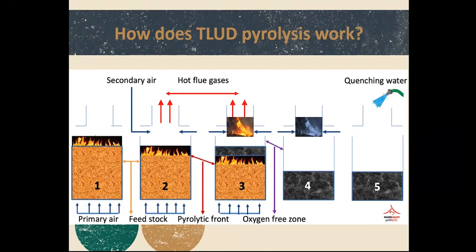So when we're done with that, we'll quench it with water, and we'll stop the process, and we will prevent the remaining material in the barrel from turning to ash. We don't want it to turn to ash. We want to pyrolyze the material so it all turns black, and then put it out so that we can keep all of that carbon-based material.